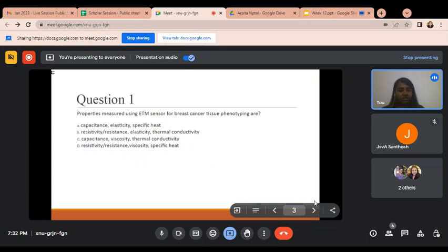Then we are going to discuss some lithography process. So if the material is deposited, then we have to do the patterning process. So we go for the photolithography process. So what happens in the photolithography process? A design or pattern is transferred from a mask to the material to which we want to transfer the pattern. So do you have any idea about the photolithography process? So first we are going to discuss the mask.